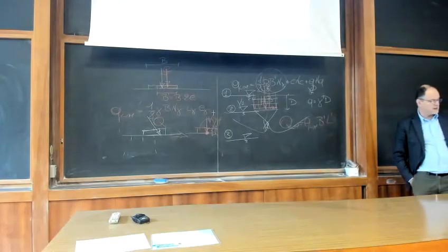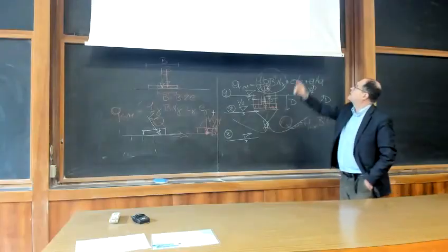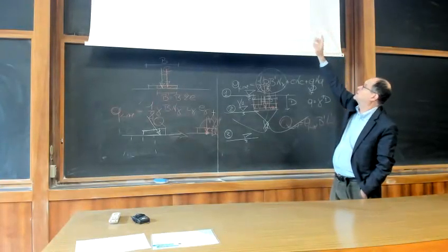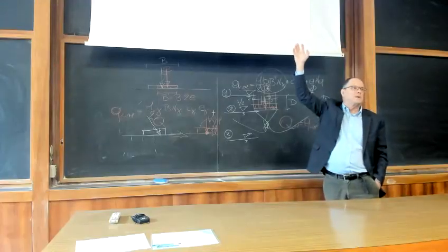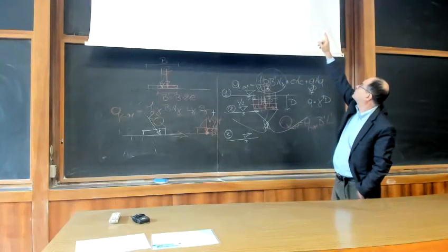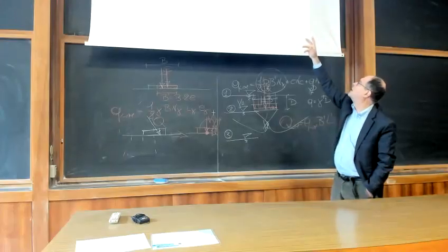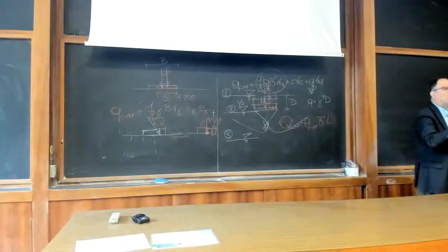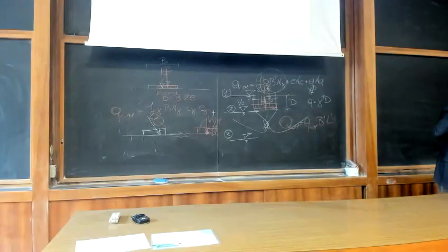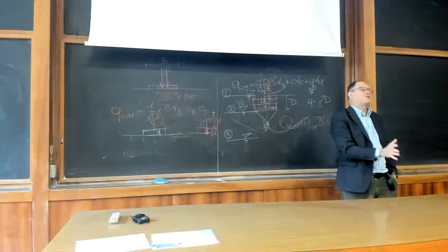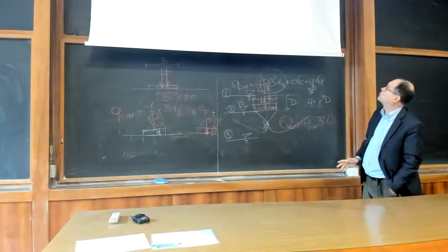Now, for example, if you take this author, Brinch Hansen in the 70s, who has provided an expression of I gamma, which is the one you see there, that is 1 minus 0.7 H over V, all to the power of 5, which is a bit odd just because it is an empirical fitting of the data Brinch Hansen had at disposal.